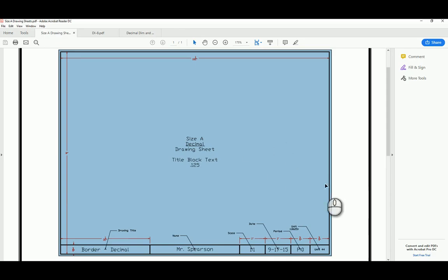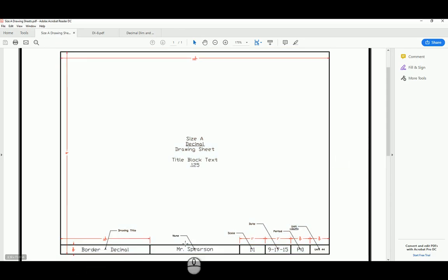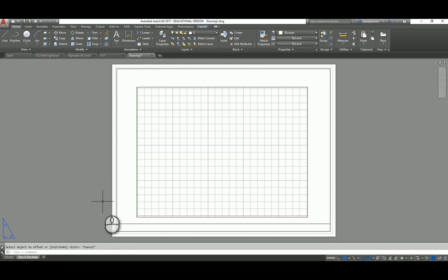If we go back to the video, or I'm sorry, the PDF, you're going to notice I have multiple screens on my computer, so I'm looking at something you guys can't see. So I'm going to go over 3.5, and then I'm going to start from the right-hand side, 3/4, 3/4, 1 inch, 1 inch. Once I get this set up, I'm going to put it on all my fields, and then we'll go from there. Here we are. L for line. I'm scrolling over. I'm not typing. I'm not clicking. I let it snap. I pull over, 3.5. I come down. I go vertical. Doing it again.